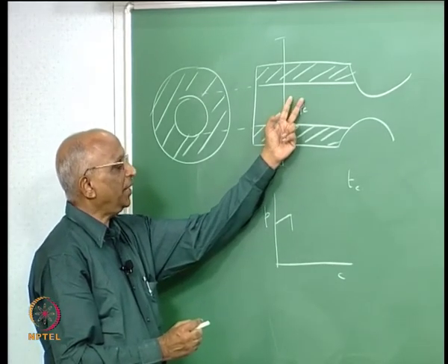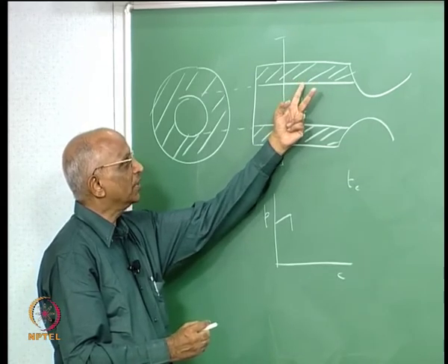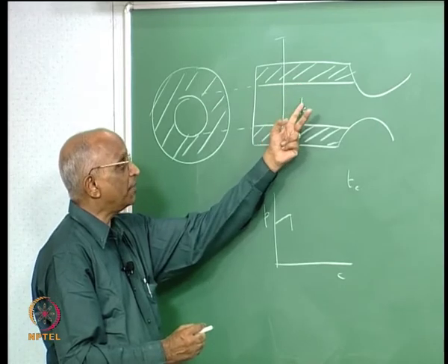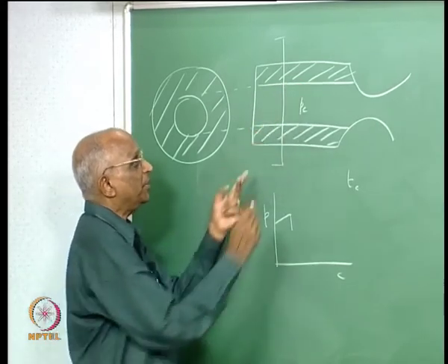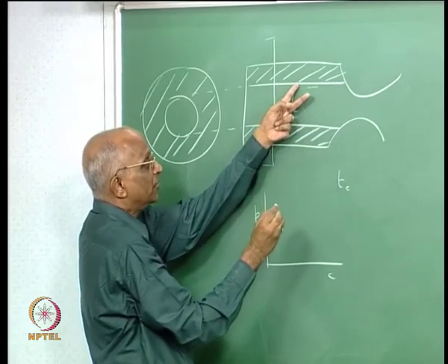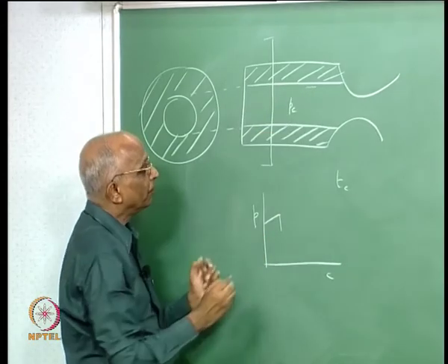The heat from the gases is still seeing the propellant, that means the propellant surface is still hot and it has a memory of the higher pressure over here. Higher pressure means the flame is nearer to the propellant surface, therefore more heat is generated and therefore the propellant surface gets more heated than at lower pressure.